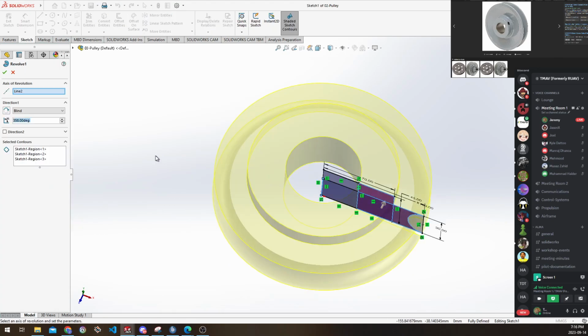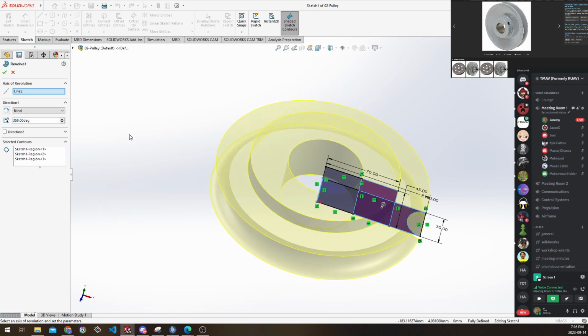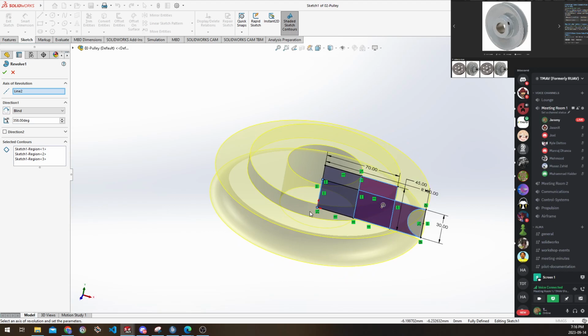I'm going to go back into the extrude. So now that I clicked that, you see we basically jump back in time to when the feature was being created. And you can see right here the issue is that this is 358 degrees and not 360, right? So you can see there's also the same options you had here as extrude.